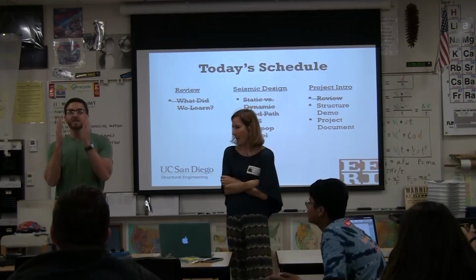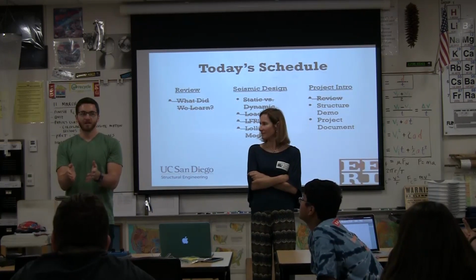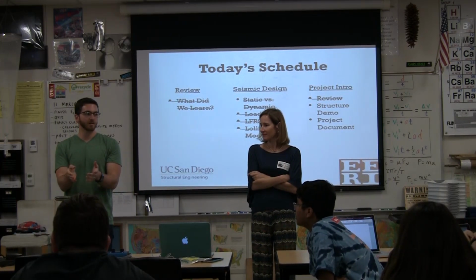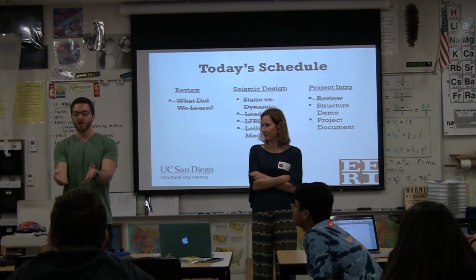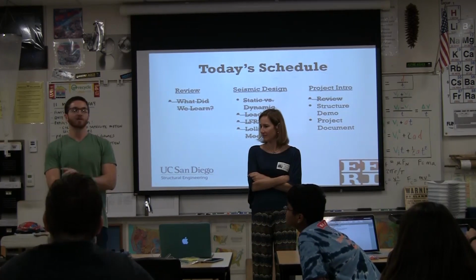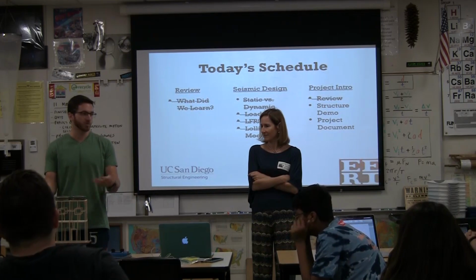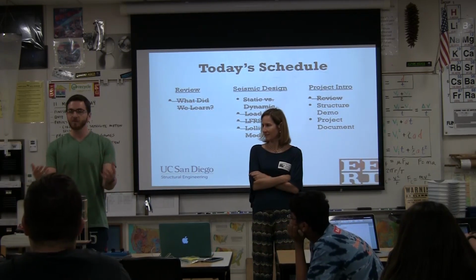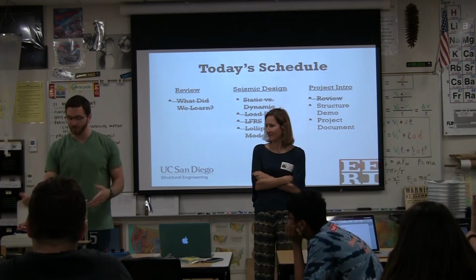Okay, so what is this load case? Is it moving? No. What is it called? Static. This is a static load case. You could call this a dead load. You might also call this a live load. This mass at the top represents the dead load and the live load. So there could be people in here and furniture, which would be live loads, and this is representing all that. It's also representing all the weight of the walls that would be built on here.